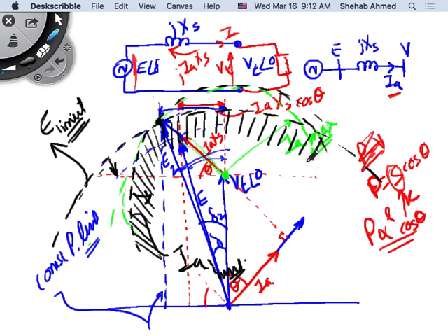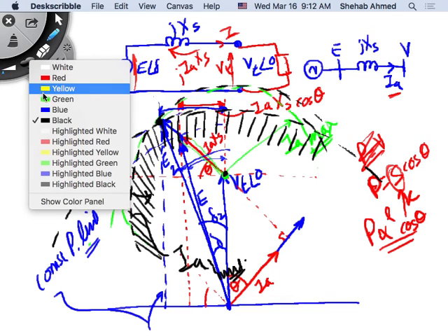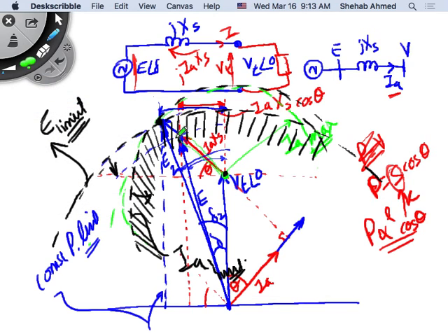Right? So a generator will have a capability curve. And of course, this is all voltage and current, right? Voltages and currents, right? You can take this and now draw the same thing on an active reactive power curve, because you have your voltages and currents as magnitudes and angles, right? So I can take this voltage here and change its angle, which will correspond to reactive power changes here. So let's draw one with a new reactive power. Sorry. So anyway, do we get this idea of operation limits of a generator?